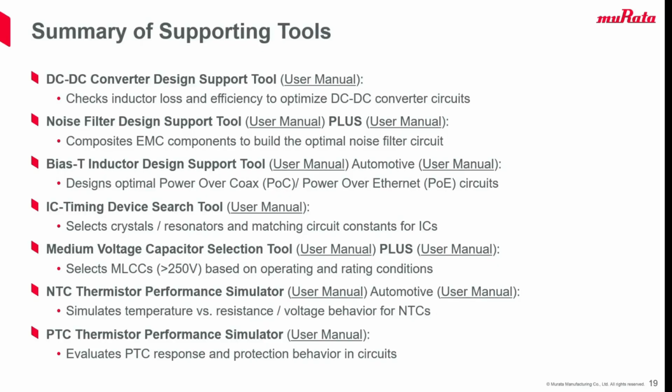Medium voltage capacitor tool. So say you're working on a higher power or resonant application where an MLCC can see a lot of AC stress. So you want to verify whether the part can handle the high voltage, high current, heating conditions safely. This covers MLCCs rated over 250 volt. And then for our negative temperature coefficient NTC thermistors, we have a performance simulator.